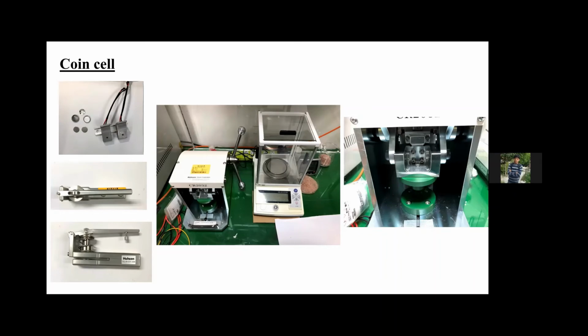First of all, we make any electrode, flexible or non-flexible, that is okay, because in a coin cell that is not important. So we can make a thin film deposited onto the current collector, and then we need to cut it so that it will fit here. For that we need a cutter.